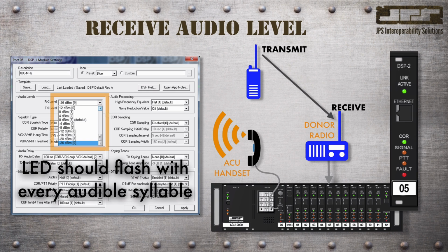Select the receive audio level, click apply, repeat until the signal LED flashes during the presence of each syllable during the test count.